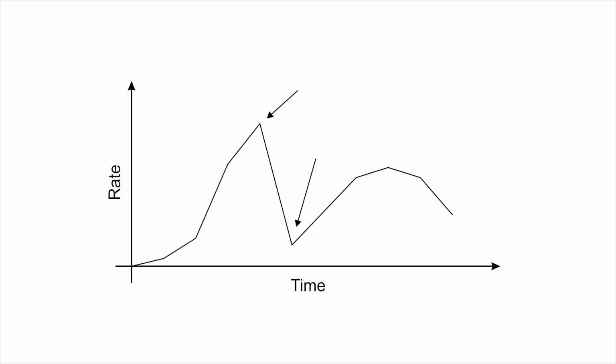And the parts that we want to focus on are these sharp changes, because that's where the motor's going in one direction and changes direction like these are, or just changes rate very rapidly, and that's where you get that tone sound from the motor changing. So if we want to reduce that top peak, what we need to do is start in this area ahead of it, and if we interpolate linearly, which is what we're showing here, it only depends on the beginning point and the end point for that range.